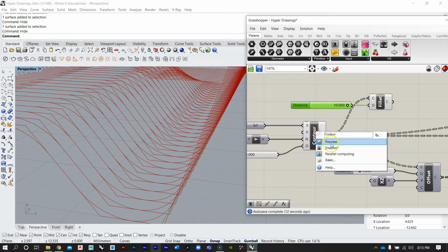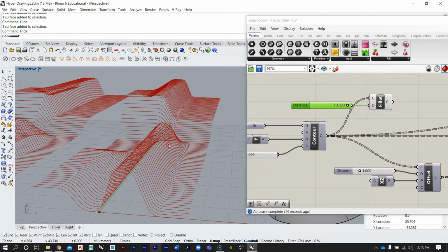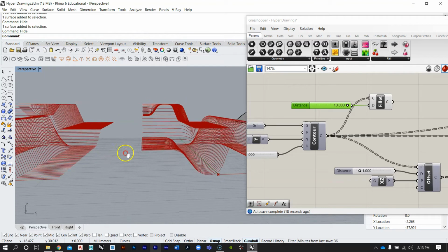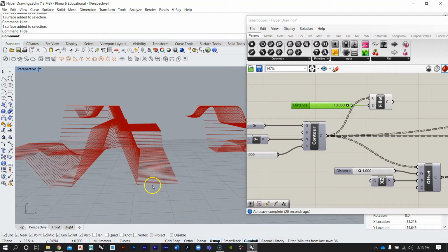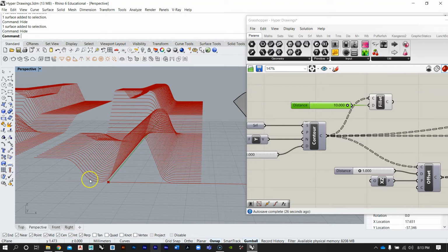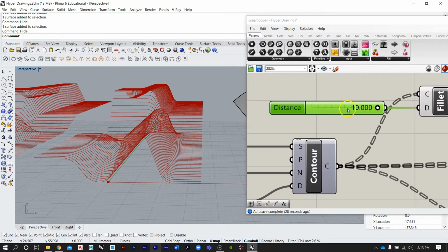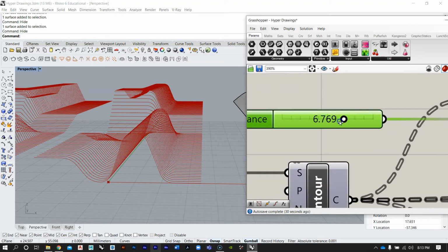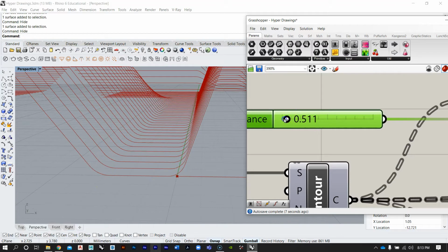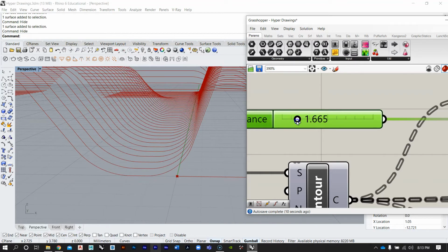So I'm going to turn off the original contours. And what you'll see is all of those sharp edges here, here, and here are all getting rounded over. And you can set this number. You can change it so it starts to die down so you can get a really tight fillet. Set it to 0 and it won't fillet at all.